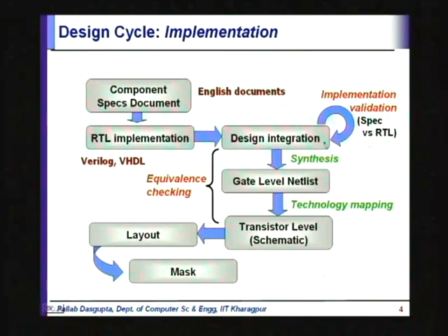Then after this design has been verified, the steps of synthesis and technology mapping, to take it from the gate level netlist to the transistor level, have the property that there is logical equivalence between these steps.